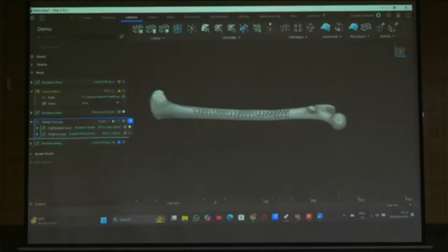Yeah, that is the problem. The simulation part you can do in nTop, but the problem is that we cannot trust the nTop results, so we are using Abaqus explicit analysis. There we did, and I used Abaqus implicit analysis, static analysis, not dynamic. In dynamic analysis you can see the real-time data. Abaqus is good to go for nTop parts to do the simulation.